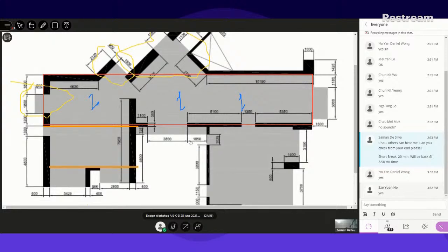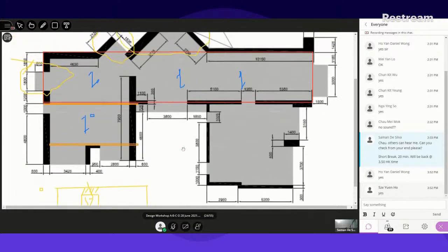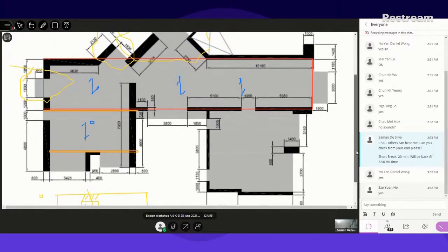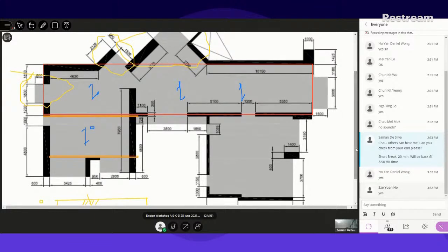This is a simply supported, continuous. Oops. This slab also can be spanning this one way, and then this one can be spanning here, and then this, I think there's a wall here. If not, you can actually have external drywall construction here, and it can support this particular slab, because you have to have something there anyway.